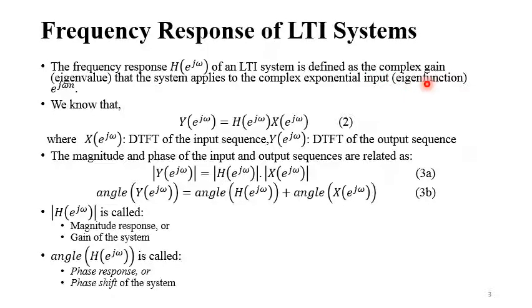If we represent a signal in terms of a complex exponential signal, then such a signal applied to the linear time invariant system will produce an output signal that is a scaled version of the input signal.